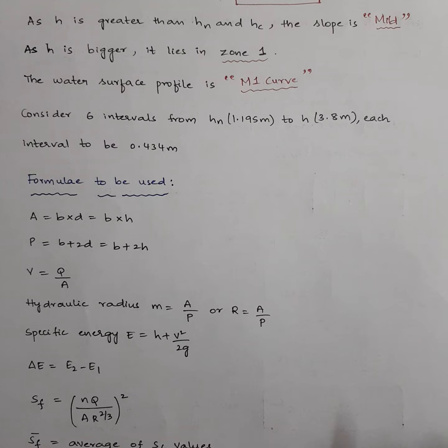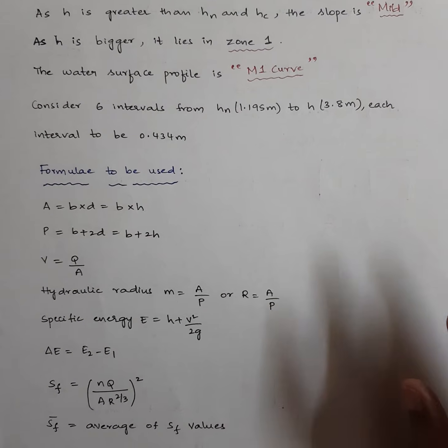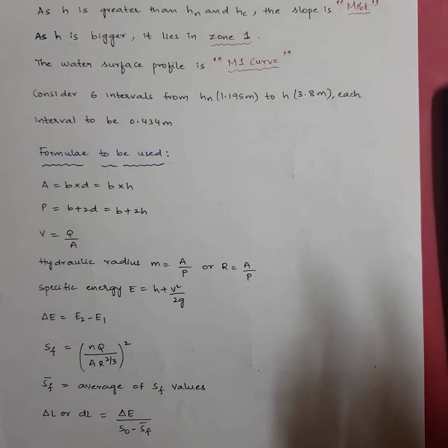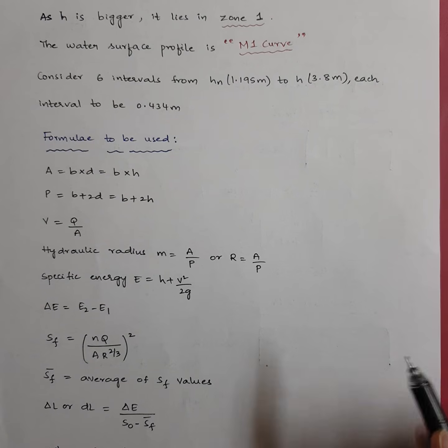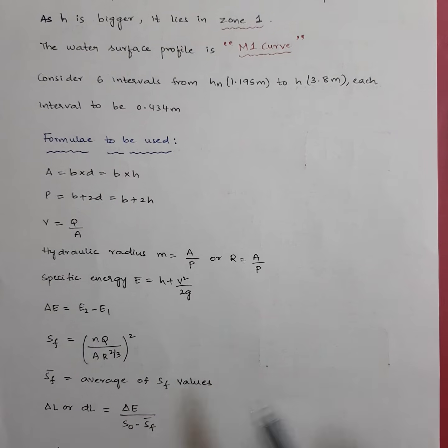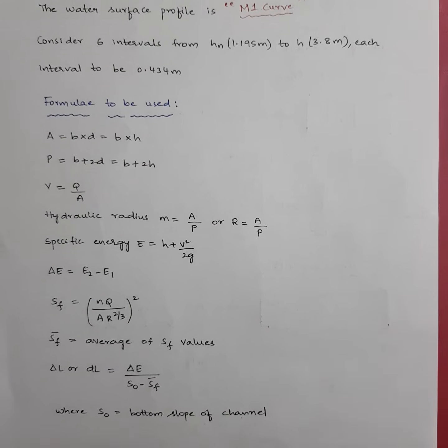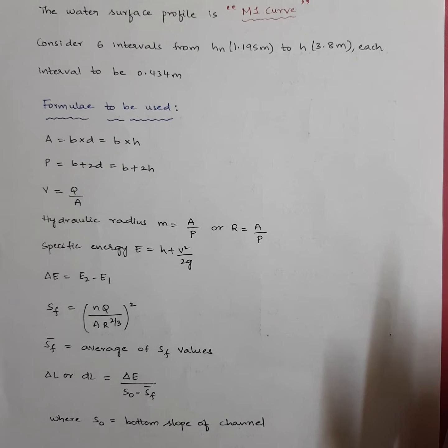Okay, so now I'll put up a tabular column related to these 6 intervals, and I'll show you how to solve for the length of the backwater curve. Please listen carefully. Before proceeding to the tabular column, just have a look at these formulae. We will be using them for completing the tabular column and for calculating the length of the backwater curve.